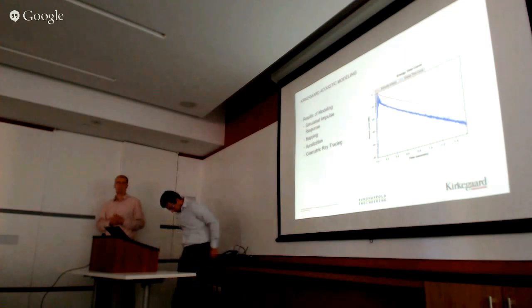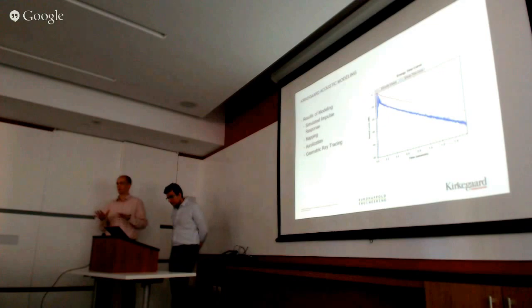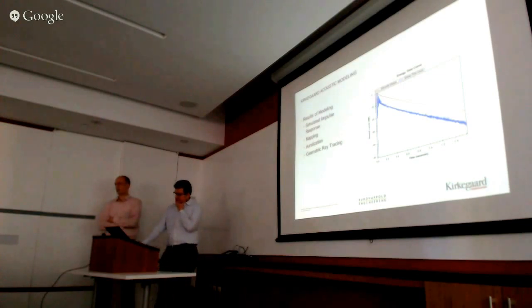What we saw on the previous slide was an example of mapping, which just shows the sound level gradient at different locations. There's a couple different ways we can do that. In smaller rooms, that would be an example of a standing wave. In larger rooms, we can look at timing slices to see, for the first 50 milliseconds, how each person in the audience gets reflections from the various surfaces of the room, and then look to treat problem spots that way.